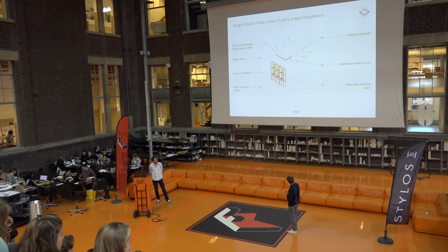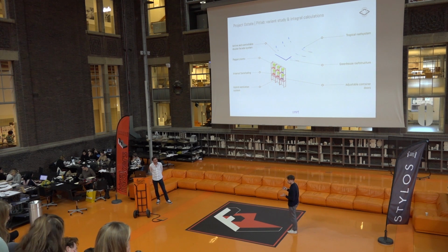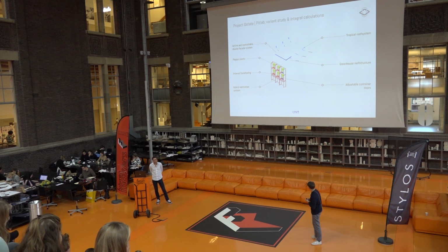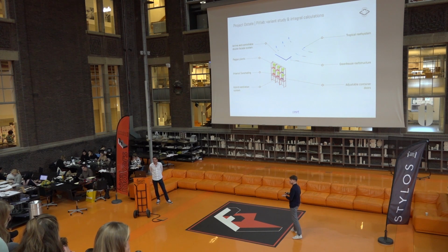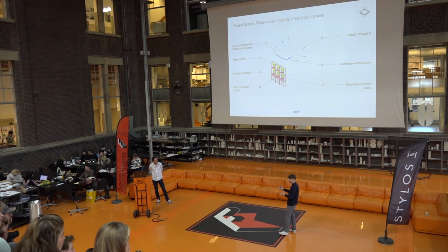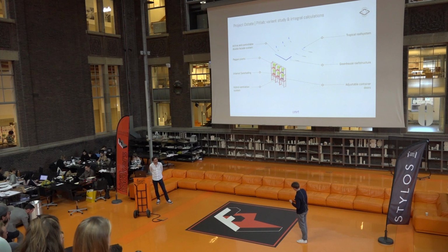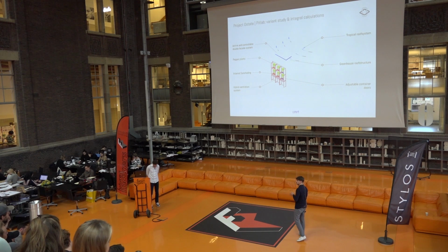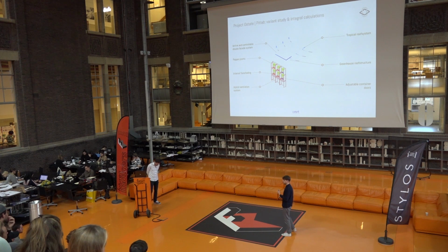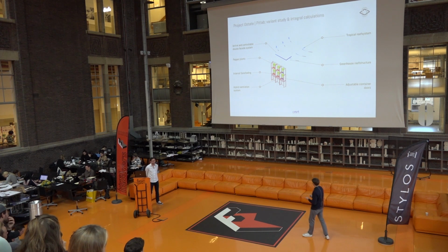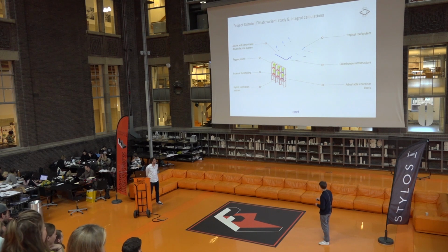So we had a lot of variables and some parameters we had to test and see what would happen. You have the double facade, the amount of plants in it, sun shading inside, the container doors which are still there, which can be of effect in terms of shade, for example. And you have the ventilation system you can play with. This is going to be natural, mechanical, in between, hybrid. So we tested all of this out.